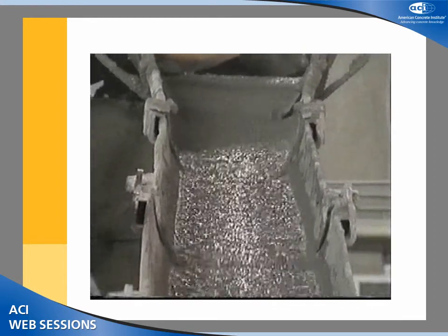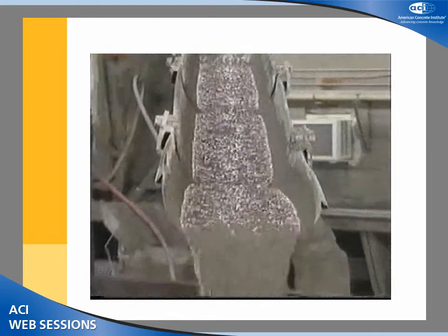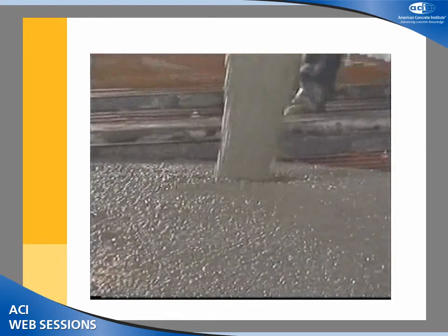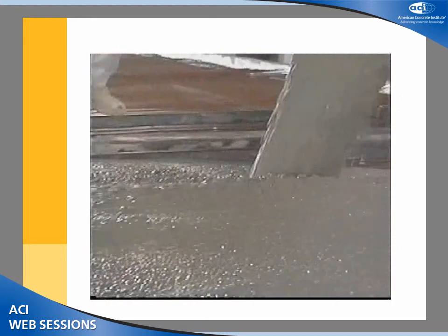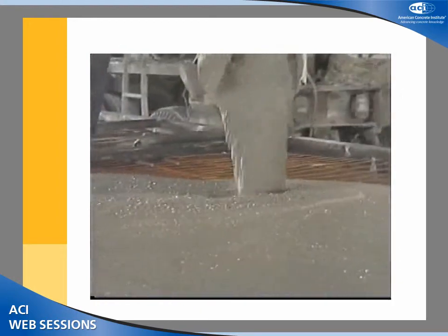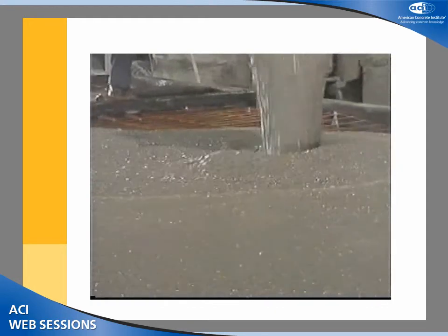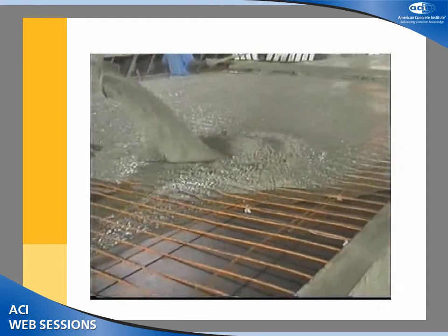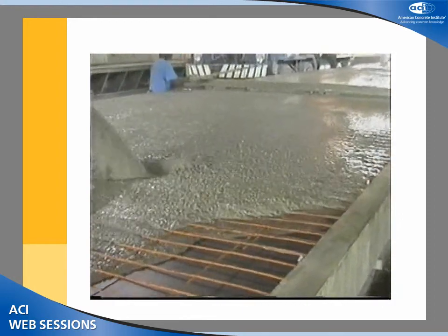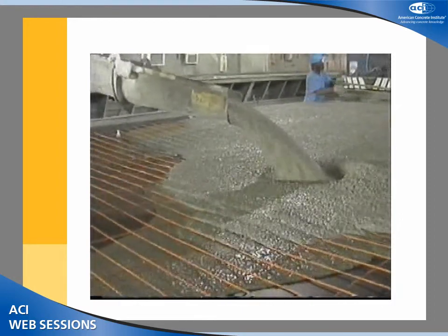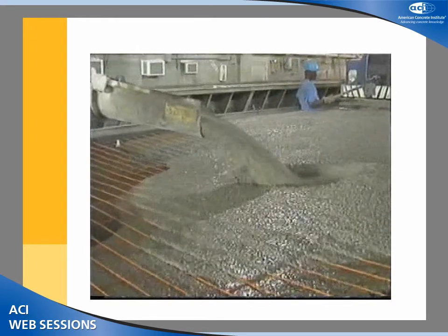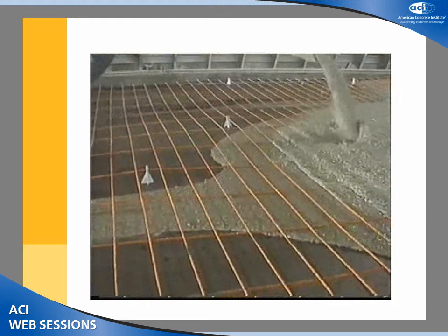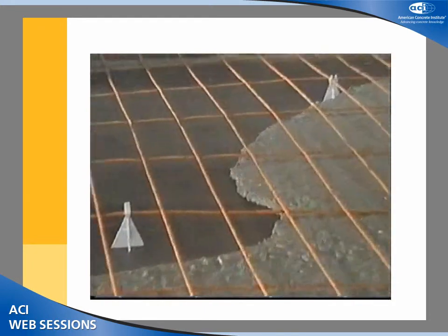The key to note here is, again, this is common for SCC, whether it's new construction or repair: the concrete has to be very fluid, but at the same time, the stone that you're using in the mix has to stay suspended in the mix. You can have a fluid concrete, but if the stones start separating out, it is definitely not good. Once again, the number of people involved in this application is very minimal. From a labor perspective, only 2 people really need to do anything: one guy in the chute, and another guy just supervising.